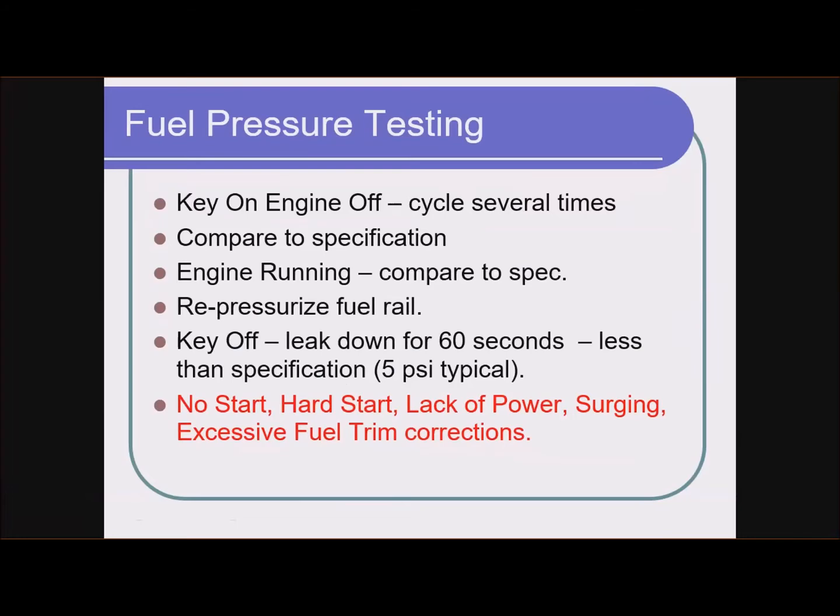You're just making sure that your electric pump is working correctly. Most GDI engines, I would say, you can look at fuel pressure, the high pressure side, on a scan tool. It's dangerously high pressure, so you need to be careful if you're working around the high pressure side of the high pressure pump.